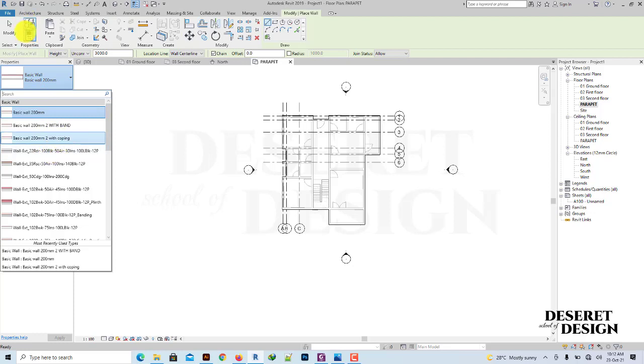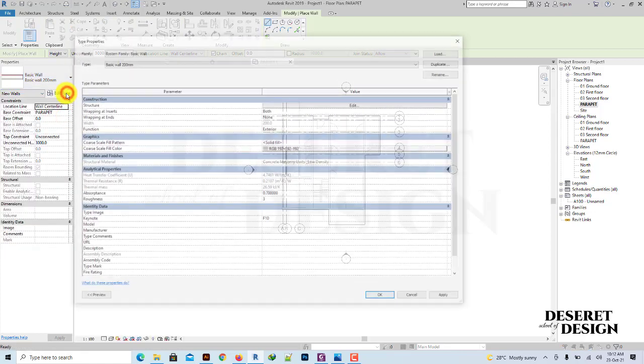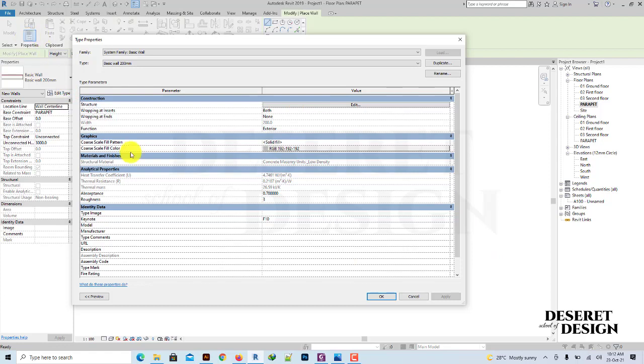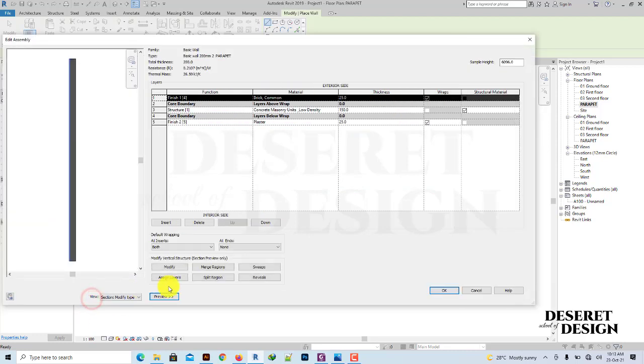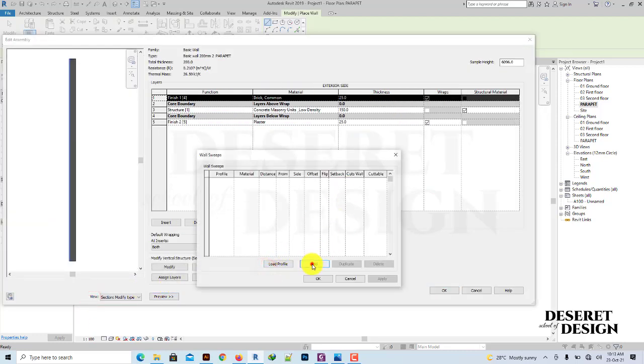Copy. Okay, anyway, let's do it. So I'll create a wall, enter into the wall. Are you following? I'll enter into the wall. I'll duplicate the wall this time. Parapet. I'll say okay. Edit. I'll go to edit. I'll show my preview. Then I'll go to sweep. And I'll add the parapet we created. We create copying 4. And I'll say okay.